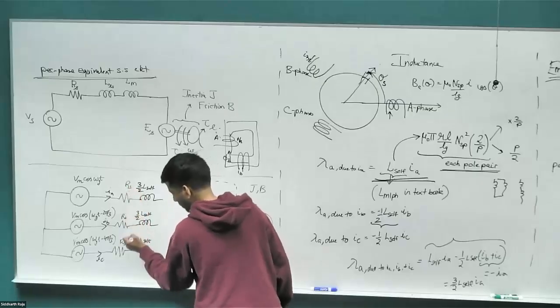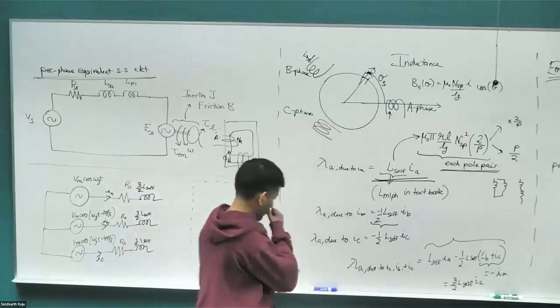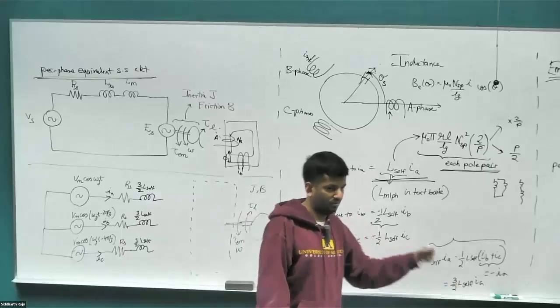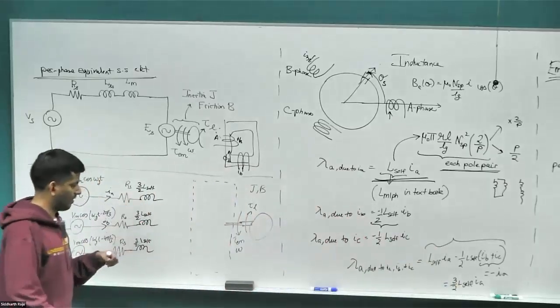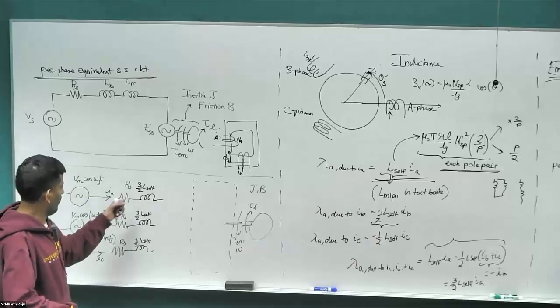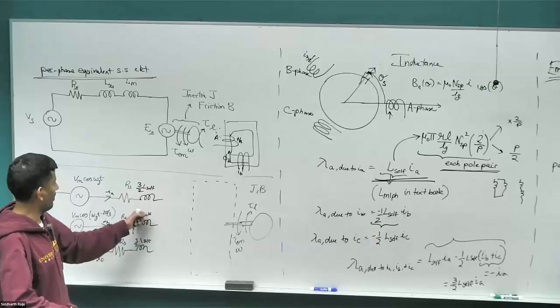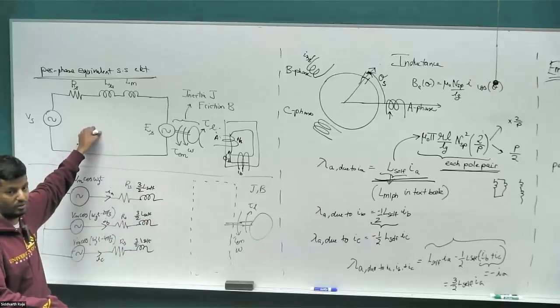Because that has embedded all the information. That's what is captured in this bottom equation here. Just a factor of taking the current and having a multiplication of 3 by 2. So that beautifully simplifies this circuit. Right? If you had to put a transformer block, we cannot reduce it into a single phase equivalent circuit at the end of the day.